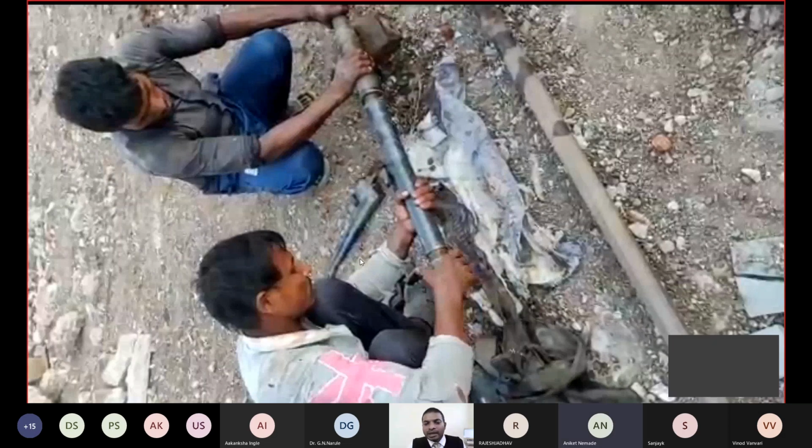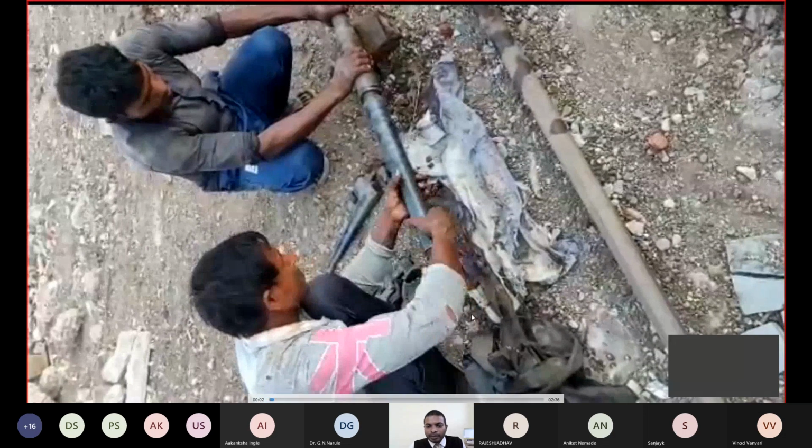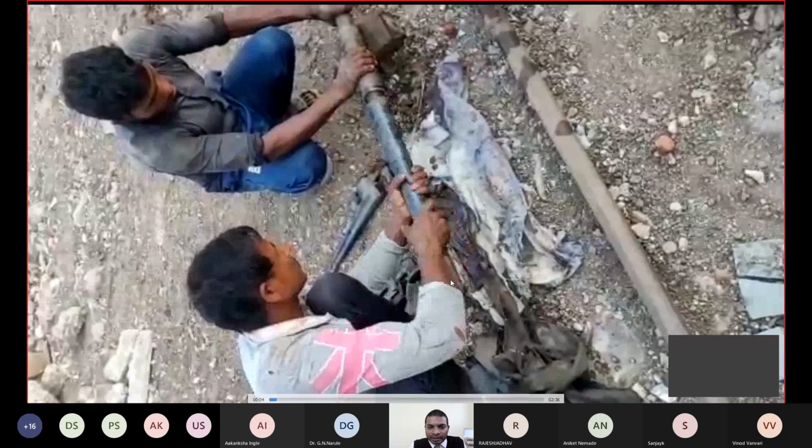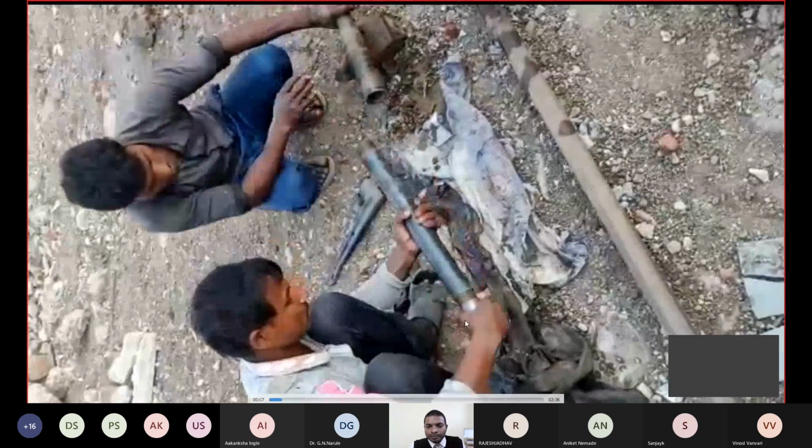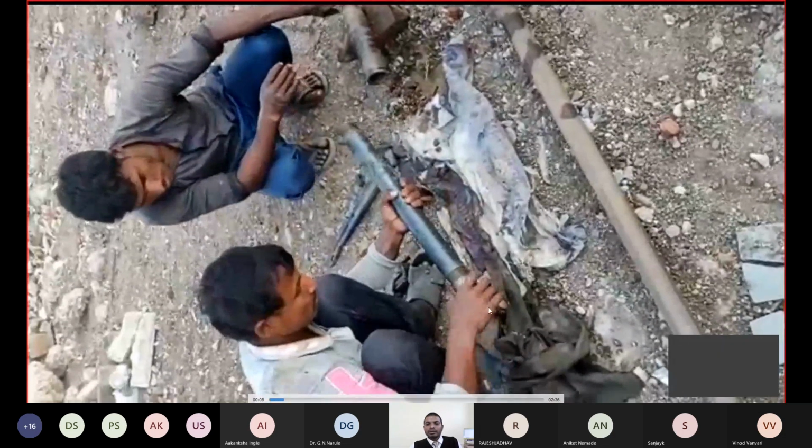Okay, after the SPT has been advanced, we have recorded for each 15 centimeters how many blows are required. The first 15 we are neglecting, and later on we take the measurements of them. So this is a split spoon sampler from which he is taking the sample out. It is the first cone by which penetration has been made, and this is your split tube.